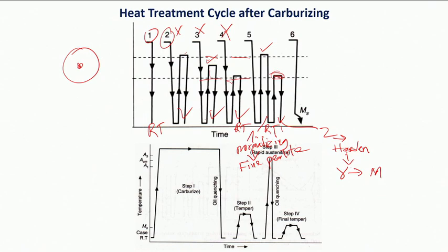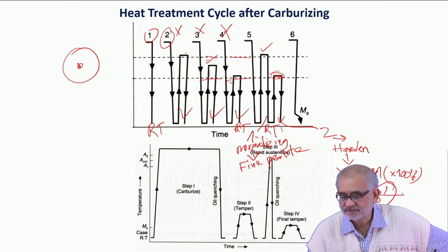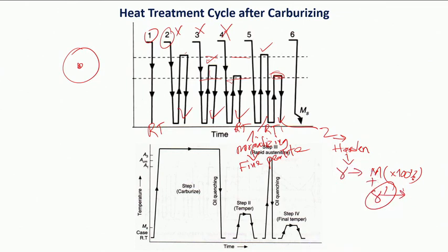But actually this martensite, what we believe to be martensite, is not 100%. If it's not 100%, then what else does it have? It is likely to have retained austenite, which is not very conducive for dimensional accuracy or the volume of the material, because during heat treatment or during subsequent use in operation due to mechanical activation, this retained austenite can convert either into bainite or into martensite, depending on the path it follows.